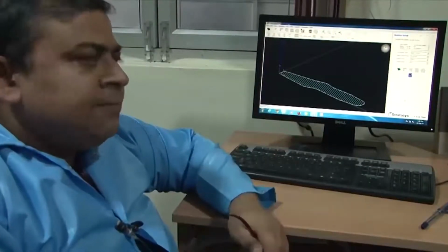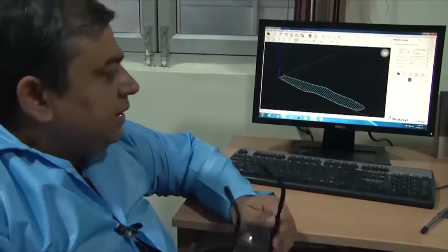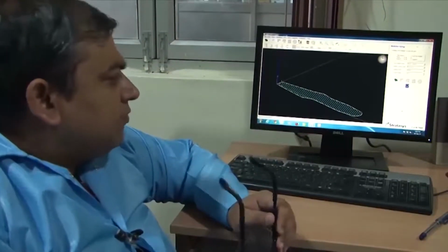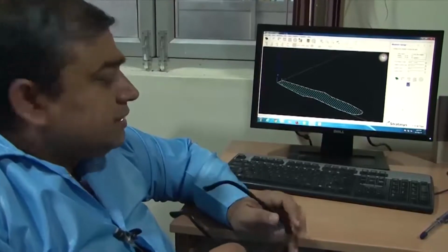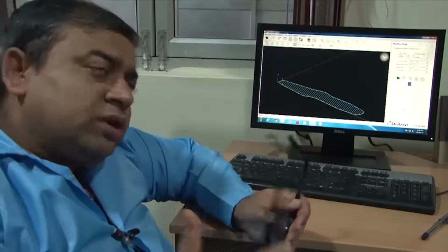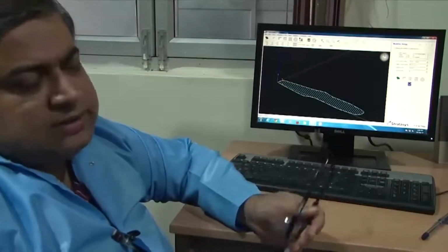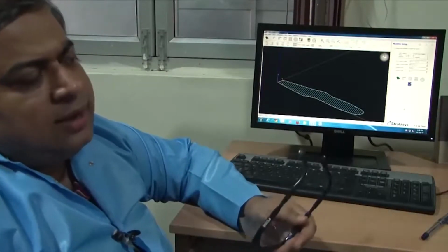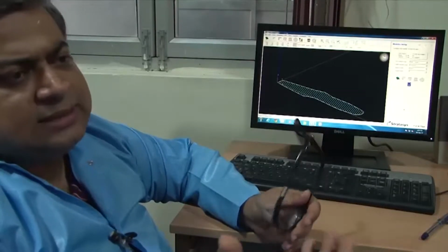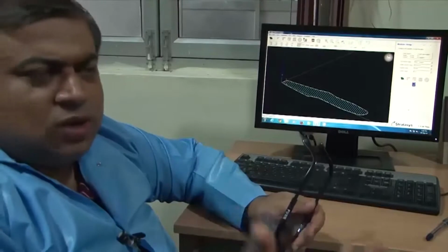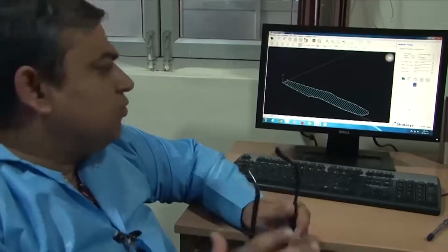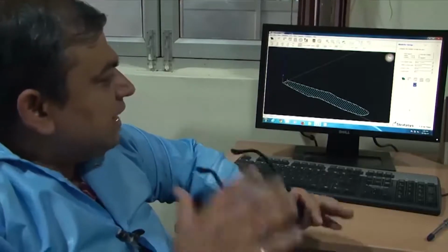So once all these things are defined, we then give the support structure of the material, and once the support structure is also defined, we do the tool path. Once the tool path is planned, as you saw, the material had a denser tool path than the support structure, which means that the support was much less material, just intended to support the material, which would be parted away later as non-useful material. Once this is done, the file is complete.